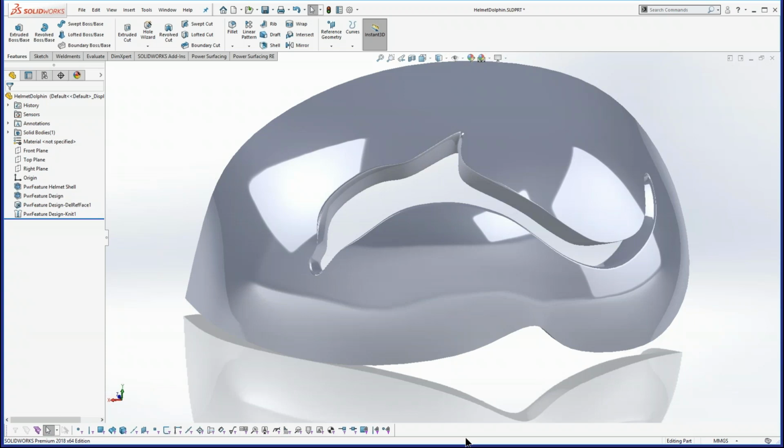So for instance, if you want to set up a parametric part that has a dimension between, say, two planes, you can dimension to those two planes, and then you can constrain to the plane so that as you update the dimension, the geometry will change as well. So that's how we handle that. It's not that straightforward because the shapes are kind of organic, and sub-Ds round off, as Susan was saying. So you have to be thoughtful about how you do the dimensioning.